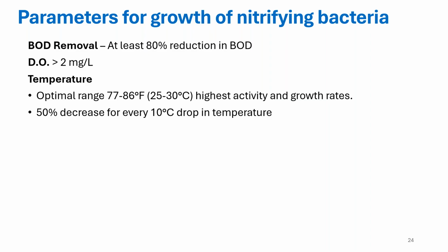As you drop in temperature, about every 10 degrees Celsius, or about every 18 degree drop in Fahrenheit, the nitrification rate decreases by about 50%.